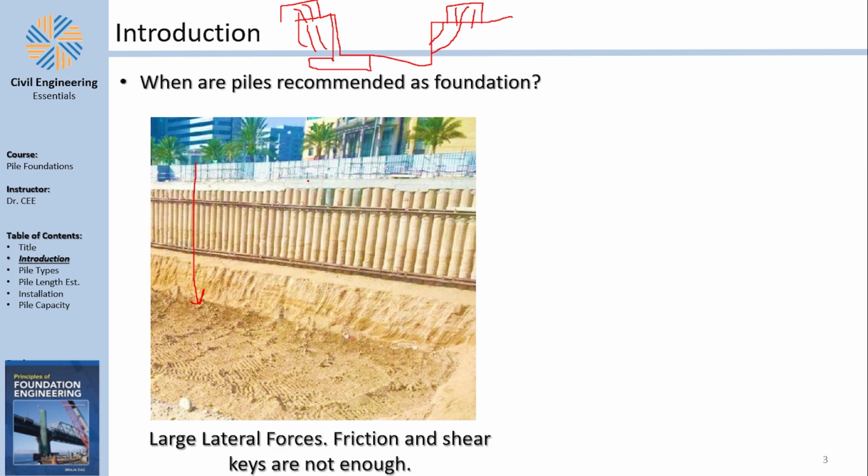You don't want any soil to be excavated here. So to do the retaining wall, you need to excavate soil. That's kind of counterintuitive. So what happens is, before we dig anything, we would hammer in piles here. While the ground is still horizontal, we would hammer in some piles to create a perimeter like this, and then we'd excavate the soil. In that case, you just excavate the soil without having any slope stability issues, and no cracks with your neighbors.